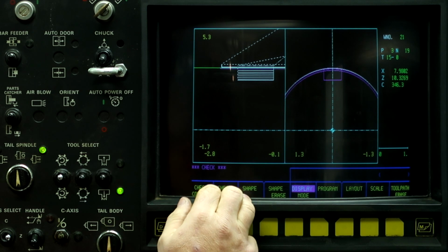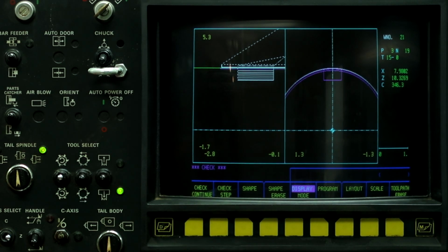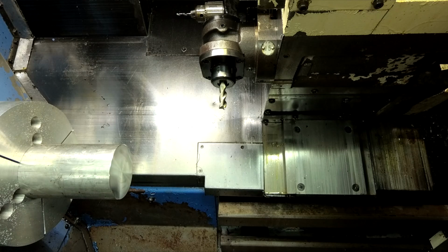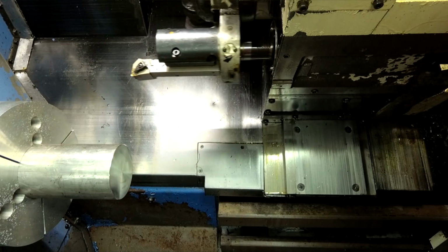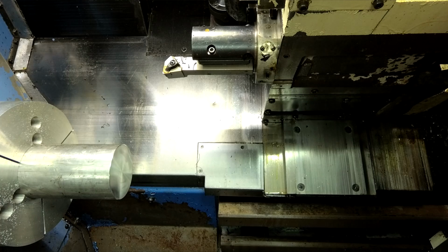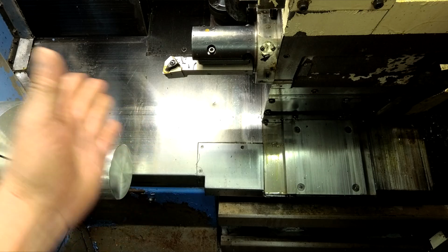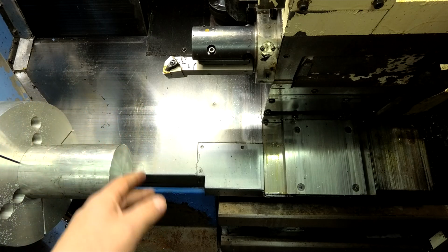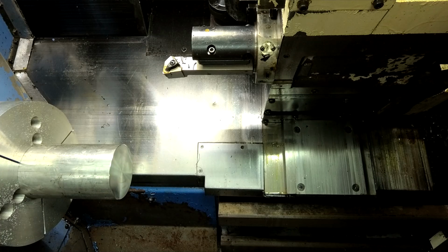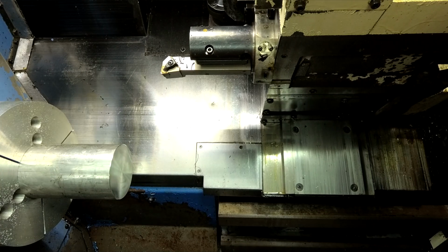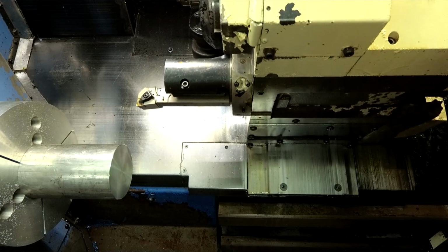So now let's go ahead and set the Z0 in this program. We'll call it up and then we'll run it. So I'm going to set Z using a turning tool. I don't want to set it using the milling tool because it gets confusing because of that 1/4 inch difference on the Z. So here's tool 16.